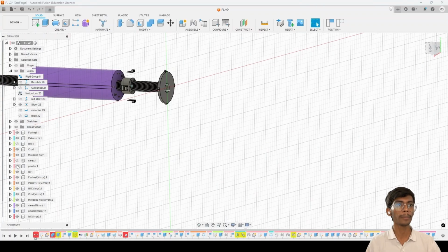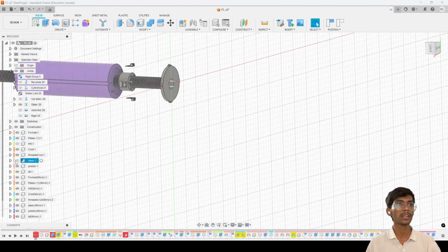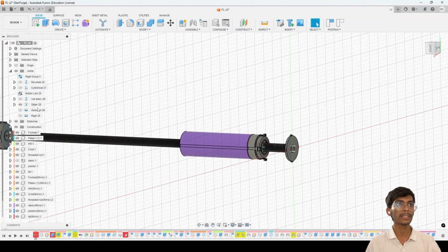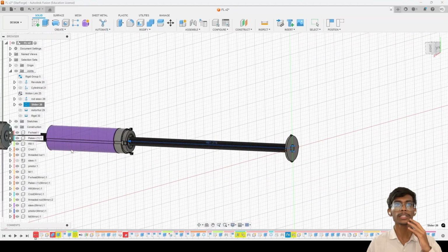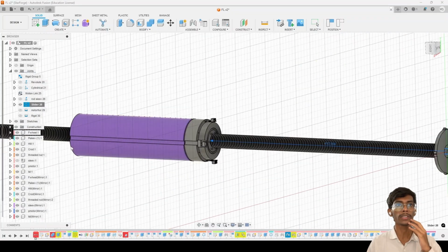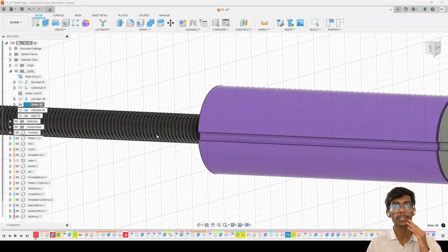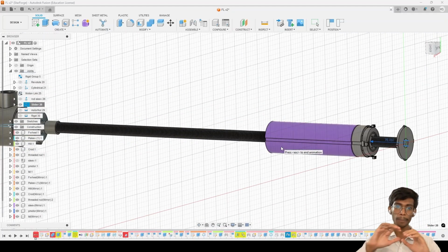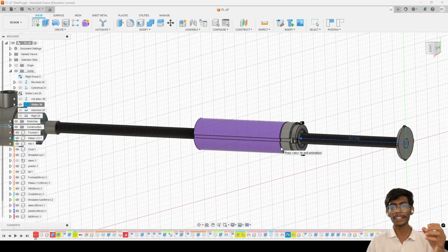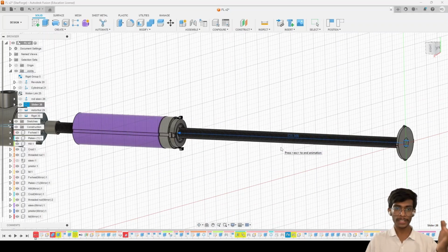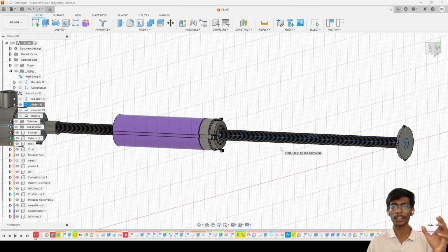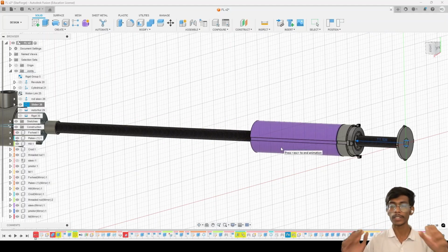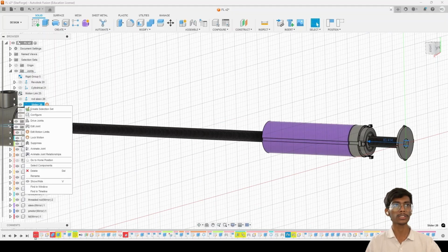And the overall impact on this hollow motor is something like this. As you can see, it is going to move forward and backwards, and these threads are going to rotate forward and backwards. What it is going to do is actually move the mass of the flywheel forward and backward, and this would give us some control over the precision and nutation involved in this device. So it is not totally random, but something that we can control. So let me just stop it.